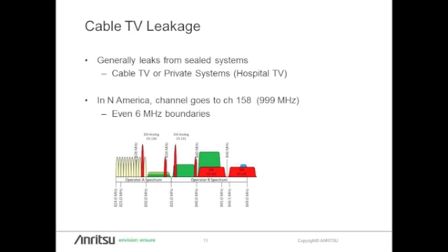And the problem here is that you really need a system to find these leakers that is capable of identifying multiple emitters simultaneously. Because you could have, in a neighborhood, maybe 4 or 5 different emitters, potentially on the same frequency, and they're all leaking. So with a traditional system, if you use, say, a Yagi antenna and you're looking around, you could look in one direction, find a leaker, look in another direction, and find the same leaker. What do you do?